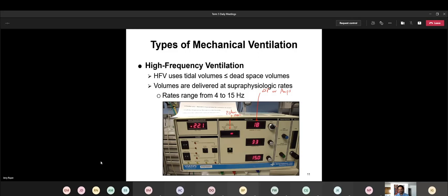So that way, after you're done setting it, lock it in place, because this machine is vibrating. It's moving, especially if it's moving at 900 cycles per minute. It's bouncing, it's vibrating. That's enough to jar that power knob if it wasn't locked, and it could change your amp setting without you even knowing it.